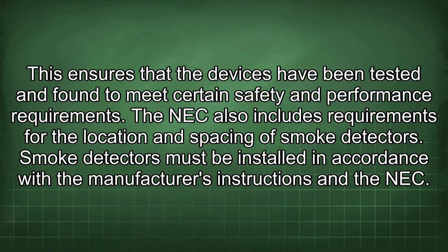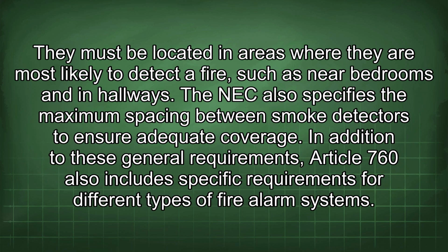The NEC also includes requirements for the location and spacing of smoke detectors. Smoke detectors must be installed in accordance with the manufacturer's instructions and the NEC. They must be located in areas where they are most likely to detect a fire, such as near bedrooms and in hallways. The NEC also specifies the maximum spacing between smoke detectors to ensure adequate coverage.